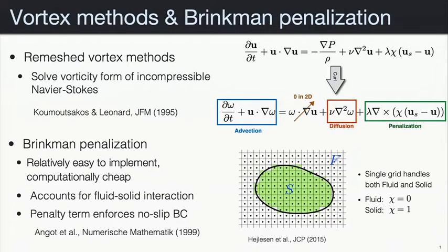Okay? And this is a very simple thing. And surprisingly, it works very well. The only disadvantage is that you have to have a lot of grid cells because, if you have a very curved surface, then you need a lot of grid cells here to minimize this sort of stair-stepping. And that's the main source of error, the smearing of the interface.